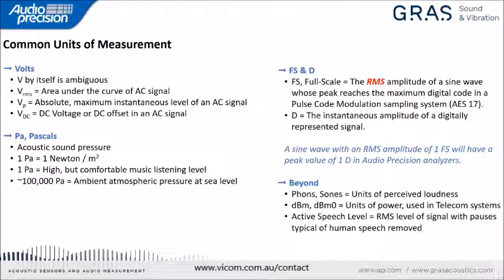However, 1 Pascal of sound pressure is riding on top of approximately 100,000 pascals of static atmospheric air pressure. So one way to think about it is acoustic sound is a very small AC signal riding on top of a very large DC offset.